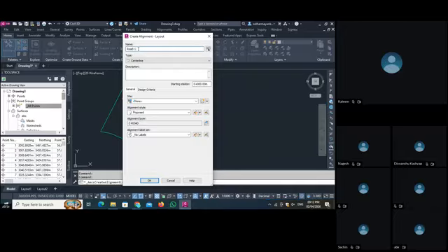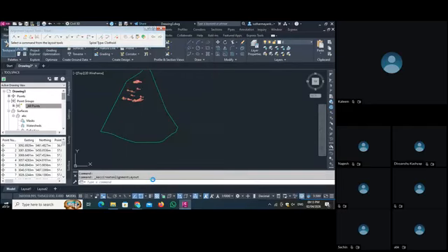See, we again give the road alignment name as Road 1. If we set no label, we go through with no label what we saw. If we set all labels here and say okay, we have this layout tools.